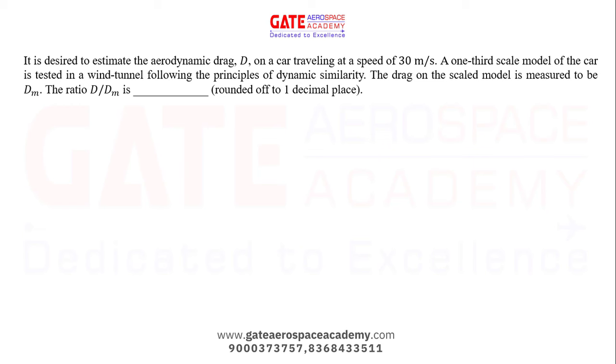Next question. It is desired to estimate the aerodynamic drag D on a car traveling at a speed of 30 meters per second. A 1/3 scale model of the car is tested in a wind tunnel following the principle of dynamic similarity. The drag on the scale model is measured to be Dm. The ratio of D by Dm is. So here viscous effect will dominate. So we have to equate the Reynolds number.